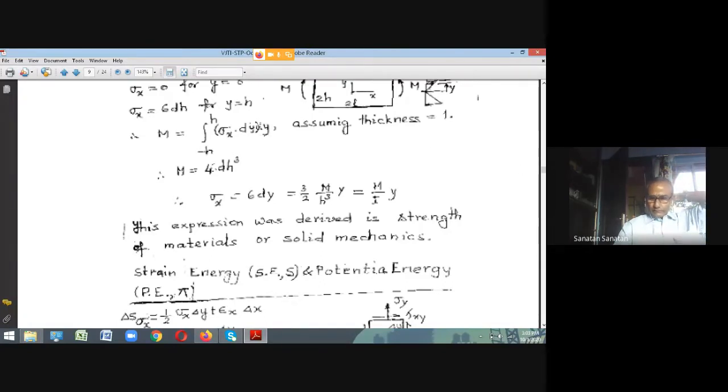To find the solution for the problems given to you, you have to find the stress functions in terms of X and Y so that they satisfy the boundary conditions. In the stress function approach, the beauty is that you have to simply determine a single function, and its expression should be such that it satisfies the stress applied at the boundary of the body.